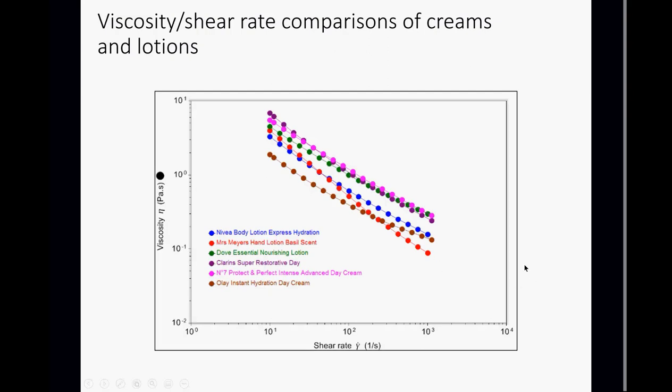Okay. What's important to note here is that some of these plots cross over, and that's really important. If you take, say, a single point measurement with a simple viscometer, then you could see the issue that you could potentially be running into here, in that the behavior at the low shear end could be the reverse of the behavior at the high shear end. So it's important to realize that viscosity is a plot and not a dot here, and we need to capture this.